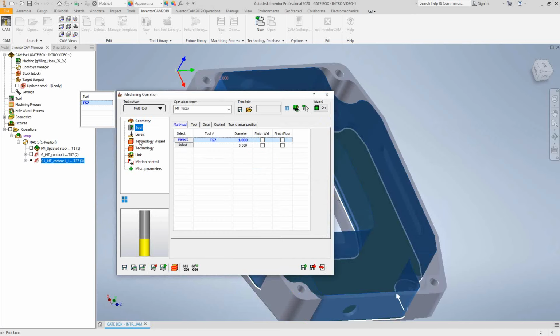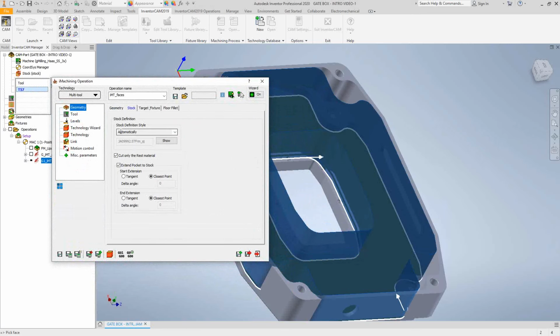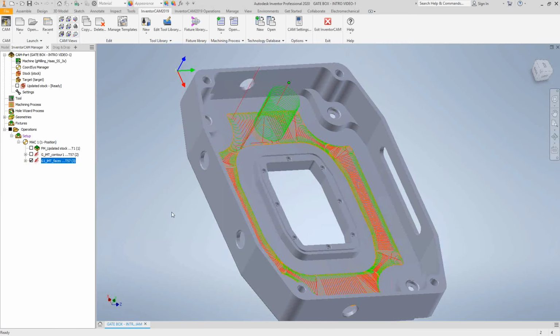Now in this case though, if we take a look at the profile, it should be recognizing as soon as I do a save and calculate that we already machined that pocket. Okay, so let's get out of here. And you can see that it's working its way only on that bottom area there. It's recognizing all the edges that we captured from there. It still does the helical entry. And you can see that there's some additional movements inside the toolpath.